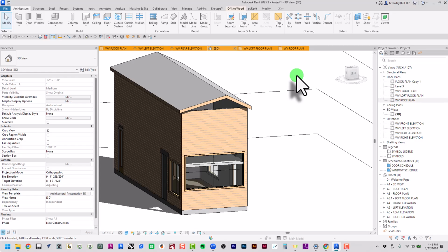This is why we want an eave, because if there is no eave, and it just falls, gets into the wall assembly, starts to get behind the finish, starts to separate the finish away from the structure, and now we've got to redo all of our walls. So the bigger the eave, the less of an issue we'll have, and also the goofier it might look.